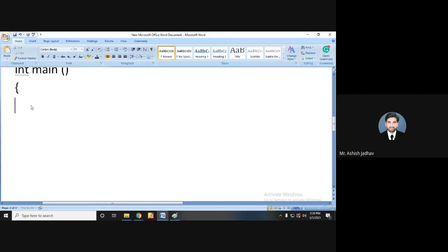So here what I will write is SystemInit, with capital S. After doing this, what will happen? SystemInit will start. What you can say is a comment. A comment can be highlighted by a double slash. So this will configure the clock. Configure the clock.